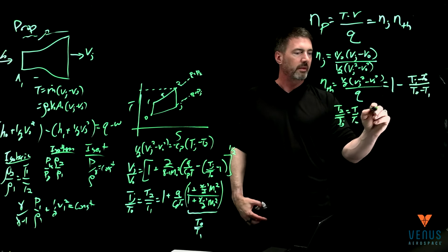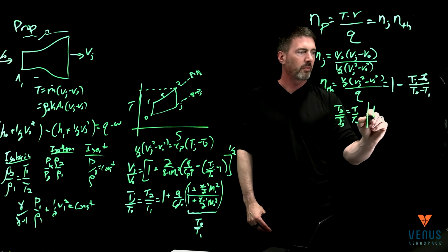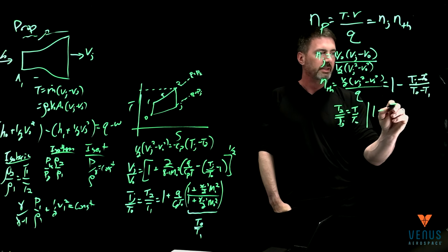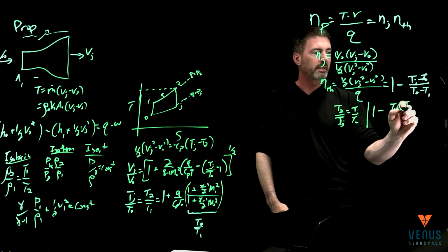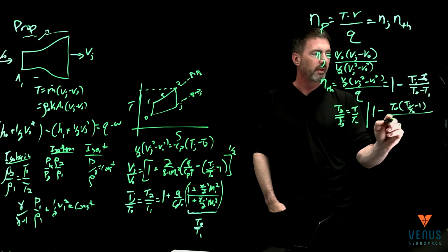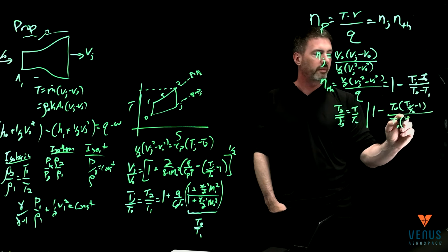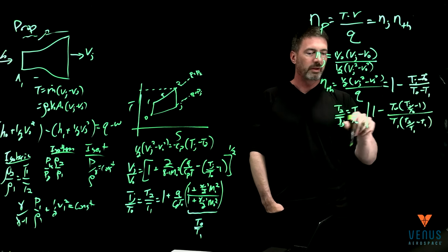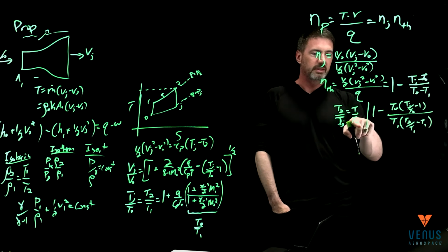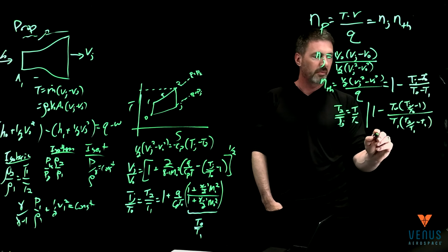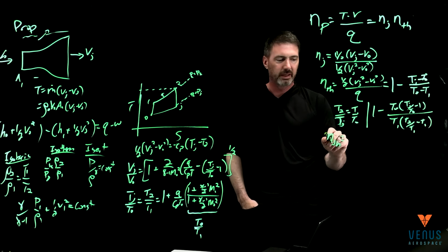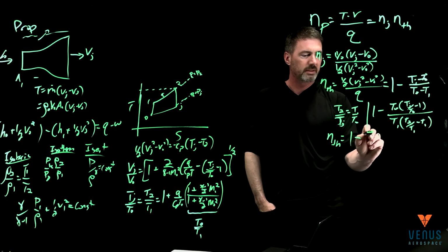So this equation becomes 1 minus, I'm going to pull the T0 out, T jet over T0 minus 1, and then I'm going to pull the T1 out, so this is T2 over T1 minus 1. Well, I just said that T2 over T jet equals T1 over T0, so those are actually the same terms. So this whole thermodynamic efficiency is actually just 1 minus T0 over T1.